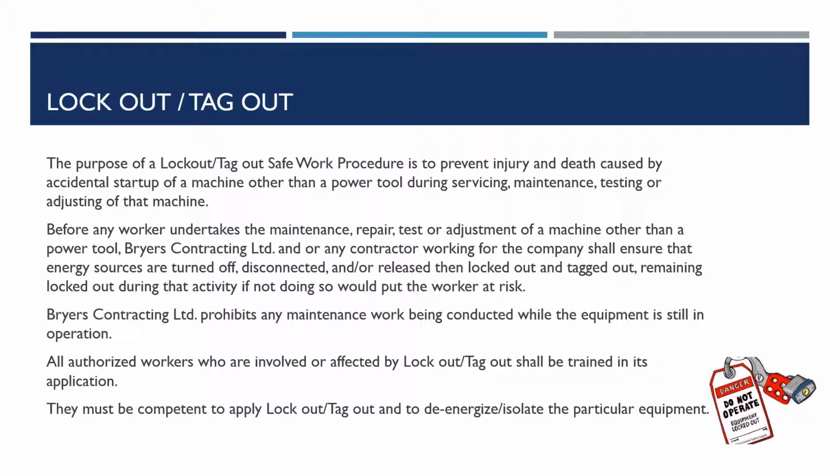Bryers Contracting prohibits any maintenance work being conducted while the equipment is still in operation. All authorized workers who are involved or affected by lockout-tagout shall be trained in this application. They must be competent to apply lockout-tagout and to de-energize or isolate that particular equipment.